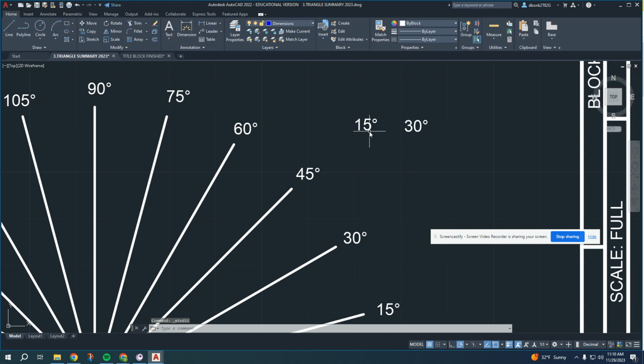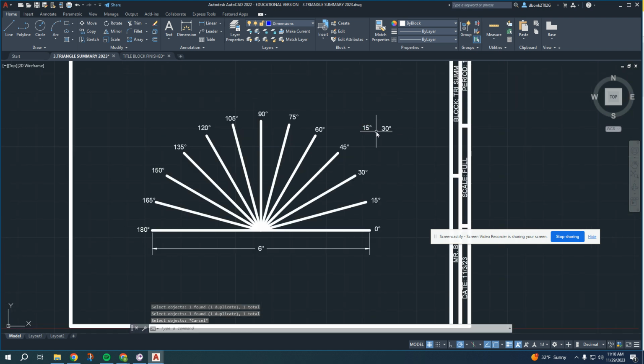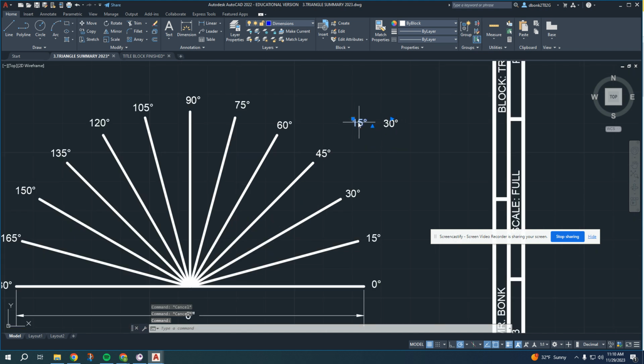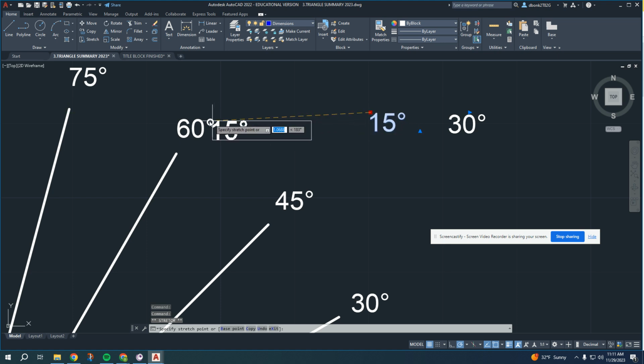The other thing is your placement of these. When you go to move text, I'm just going to hit escape. When you click on it, nothing else. Escape, escape, escape. Click it. You should get these 3 points, a box, and two triangles that will allow you to move it. You have to be zoomed in order to get text placed the right way. Some people are trying to control this from too far out, and it won't go exactly where you want it to unless you're actually zoomed in close.